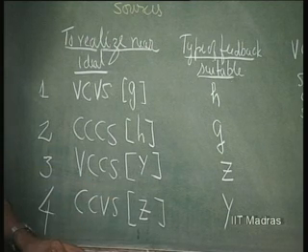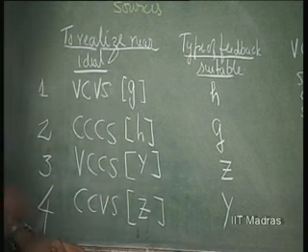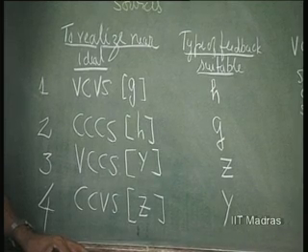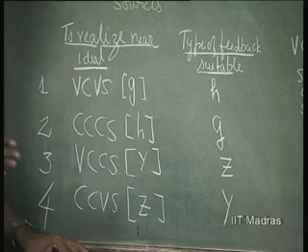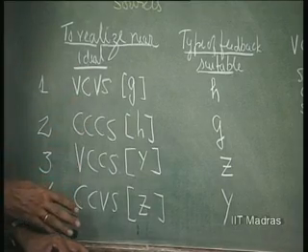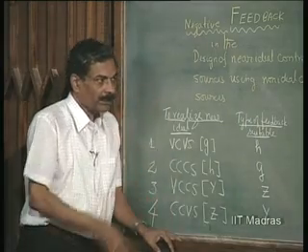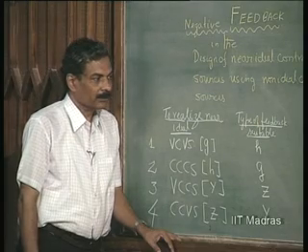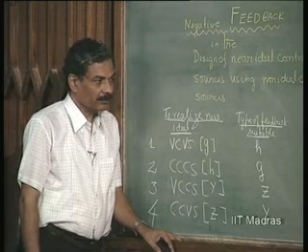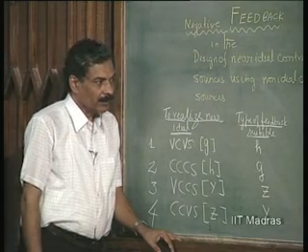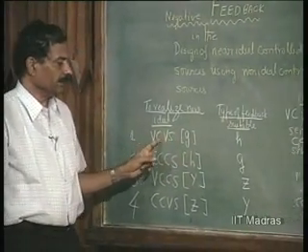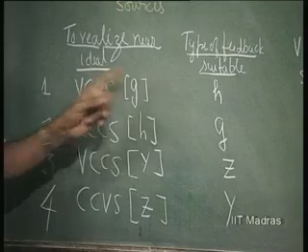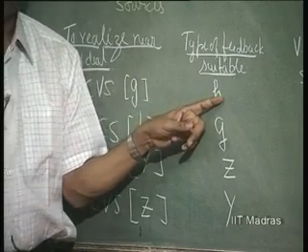What we mean is that all the other parameters will go towards 0 except for the forward transfer parameter, which only exists as far as these ideal sources are concerned. Now, how is this idealization going to be achieved? The type of feedback that is suitable for VCVS is obviously H feedback.